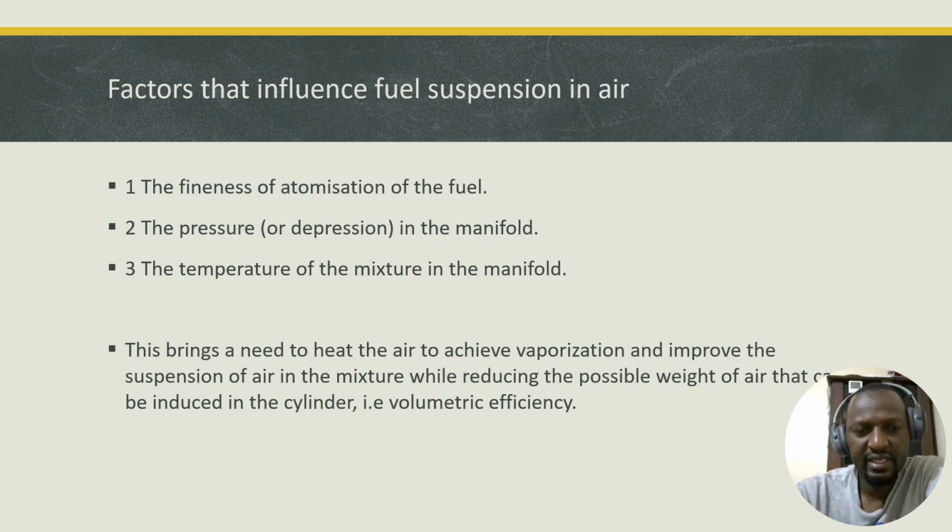Now, the factors that influence the fuel suspension in the air, or how the fuel is carried in the air, are, one, the fineness of atomization of the fuel. The finer the atoms of fuel, the better they will be carried in the air. Two, the pressure or depression in the manifold. The higher the depression, the better the atomization, because that is what actually draws the fuel and breaks it up.